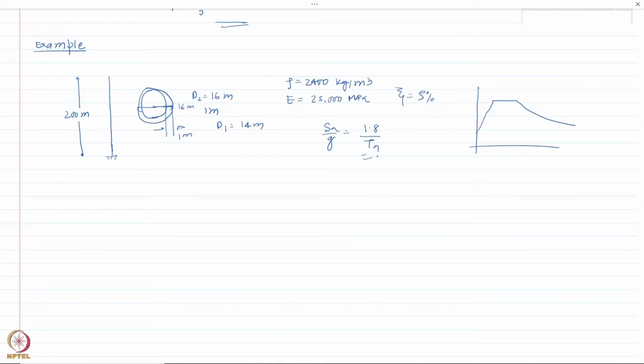See, in this type of problem, the first step is always to determine the section parameters and the modulus of rigidity, the flexural rigidity and all those things, so that we can find out the solution. And then assume the shape function. Now for this case, you can assume the shape function to be 1 minus cos(pi x by 2L).